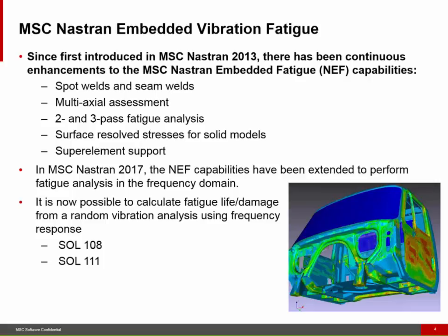Now in MSC Nastran 2017, we will extend the NEF capabilities to also offer the possibility to perform fatigue analysis in the frequency domain. That includes new technology for random response and deterministic simulations for fatigue life and damage assessments in the frequency domain. And you can do that both in direct and modal frequency response, meaning both solution 108 and 111 are supported, together with also solution 200, the optimization solution sequence.